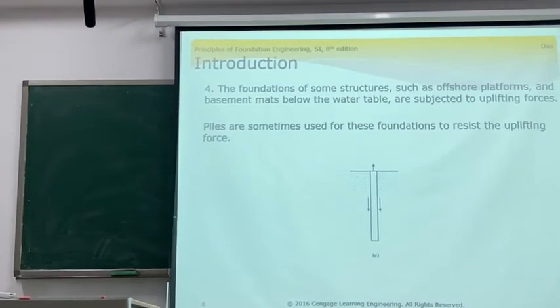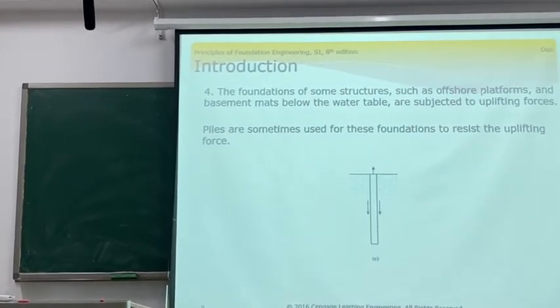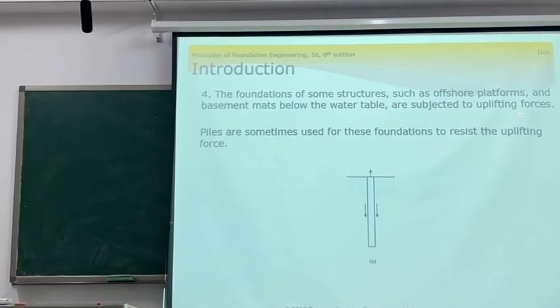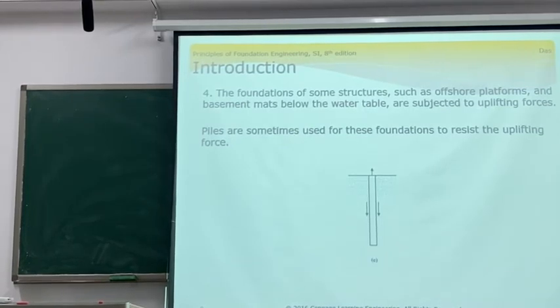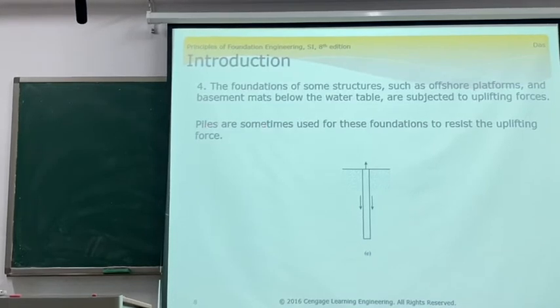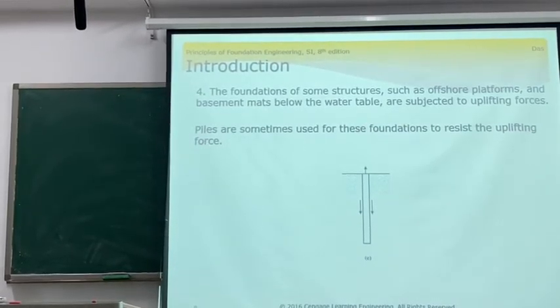And the first condition is the formation of some structure such as offshore platforms. This is nearby the sea or river. And the basements made below the water table are subject to the uplift force. Piles are sometimes used for this foundation to resist the uplift force.